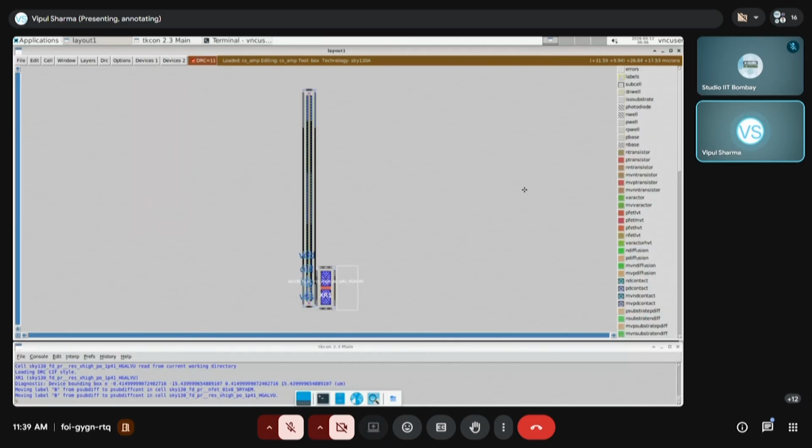But if you are doing a complex circuit, like a circuit which has many components, you would avoid putting them in manually here, because there is a chance you might miss something. It's a good habit, a good practice, to import the netlist which you actually use for validating your front end design, and import everything here. So this way everything got instantiated here.